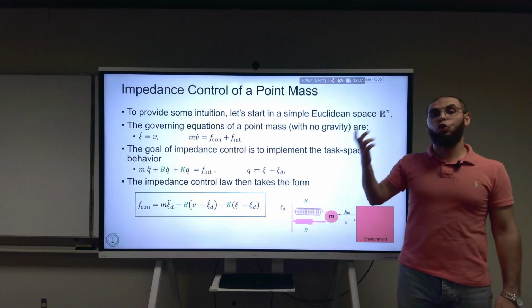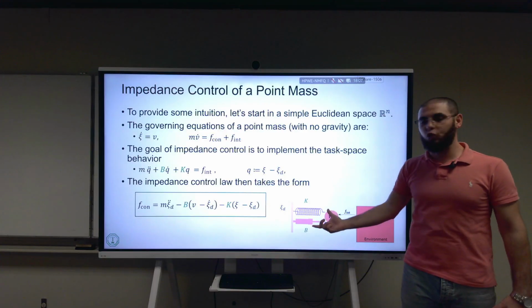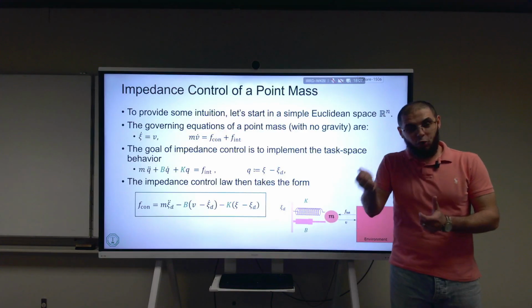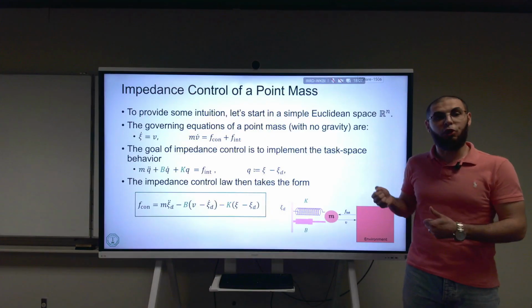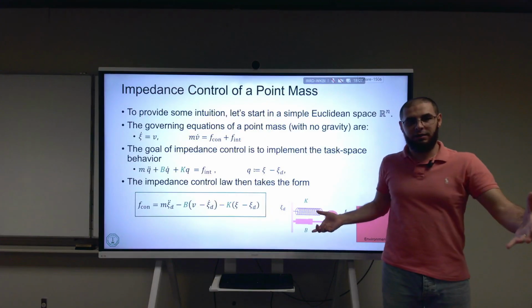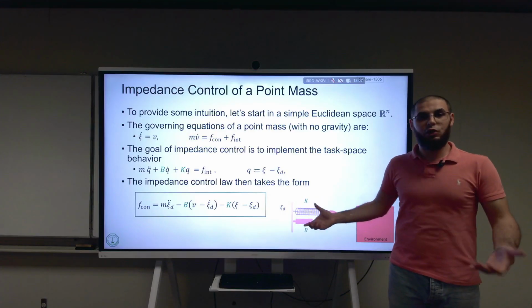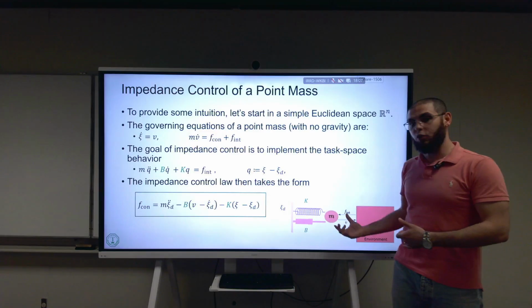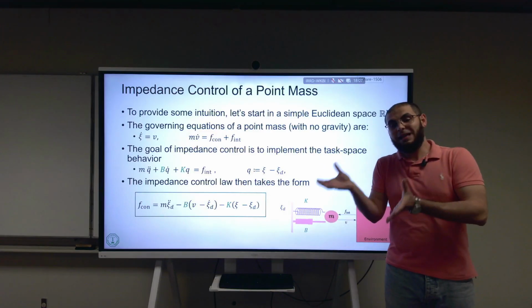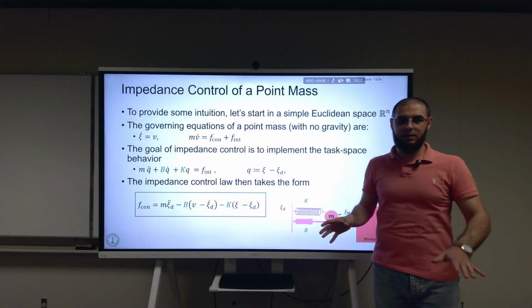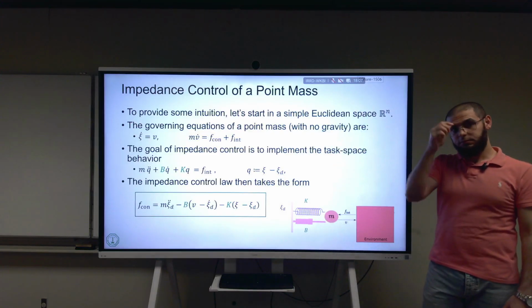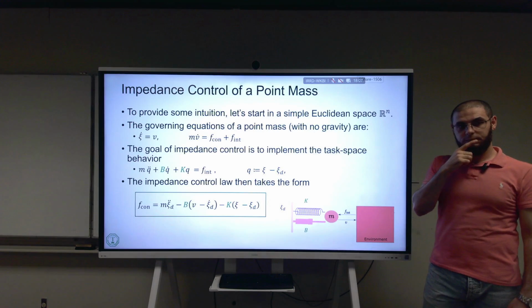So now you no longer think of the controller as a proportional term and a derivative term. The proportional actually is emulating, is replicating a virtual spring and a damper. When you combine that virtual spring and damper with your mass, you get a mass spring damper of the whole closed loop system. But what is the relation of this spring for the system with the environment?